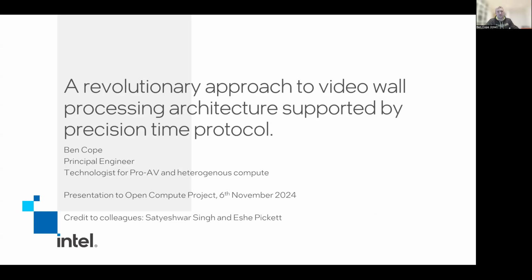Yeah, I think I kind of see where you're coming from. So Sisha's right that from the PC, it doesn't care. But what I think you're referring to, and we haven't done yet, to be honest, is if you had an IP stream of video coming in, maybe using something like SMPTE 2110, if you know the protocol, where it will stream the video in. We haven't taken the time reference from that and locked the display to that so far, which would maybe be how you do that sort of thing for minimum latency and to avoid some of the filming artifacts. That's maybe something someone could do with this.